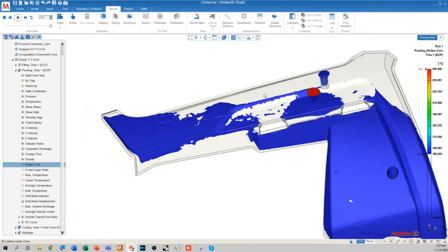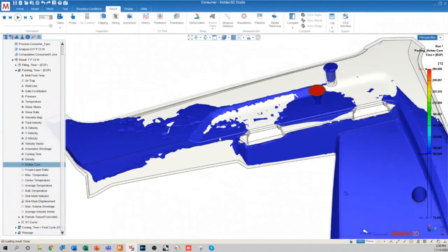However, the material between those two regions is kind of stuck in limbo because it's at the coolest temperature in our geometry. So the material at the middle of our flow, the material between the gate and the end of fill region, is going to solidify, separating the gate from the rest of our part geometry. And it causes this sort of pressure concentration.